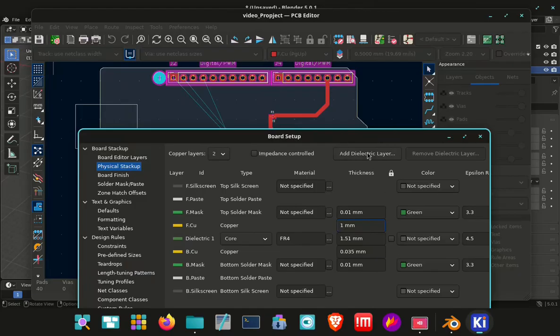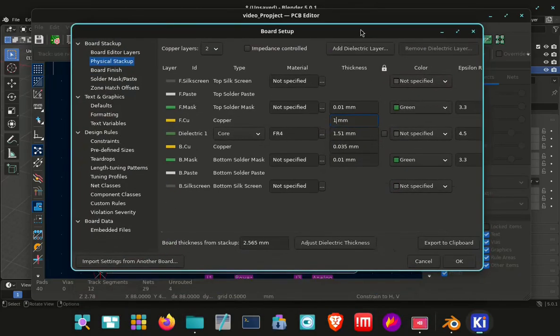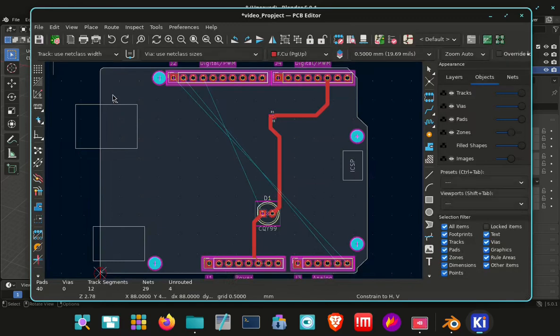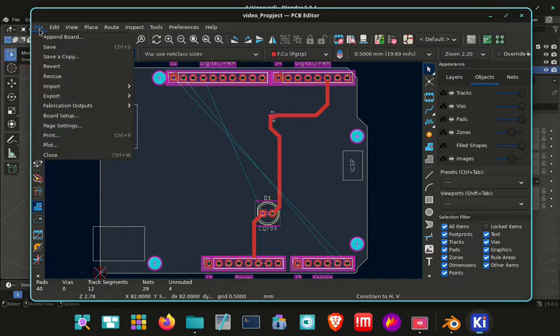which is great for a PCB that's being etched. But for us, we need it to be 1mm thick on the actual plate, so we can actually cut the copper out. So that is okay. And then we have to save it. If we don't save it, all of that just stays in the memory, but it doesn't update what you need for exporting. So we save there, and then we can export. If we don't save it first, then you'll just get the same output again.